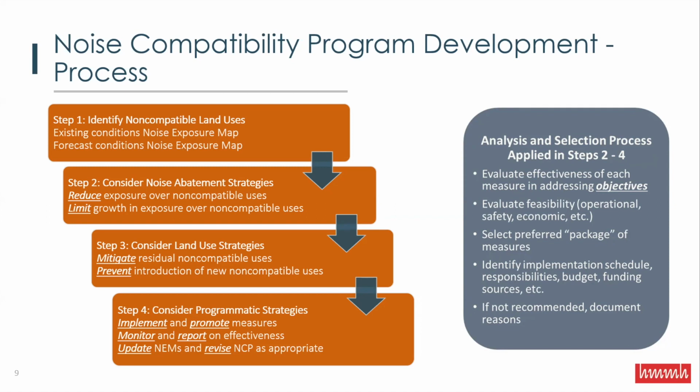Evaluate the feasibility. Operationally, can you do it? Safety-wise, would the FAA allow it to be done? Economically, is it causing unfair disadvantage to any operators at the airport? And then you select your preferred package of measures and identify with those measures the schedule for implementation, who's responsible, where the funding is going to come from, and how much it is going to cost.